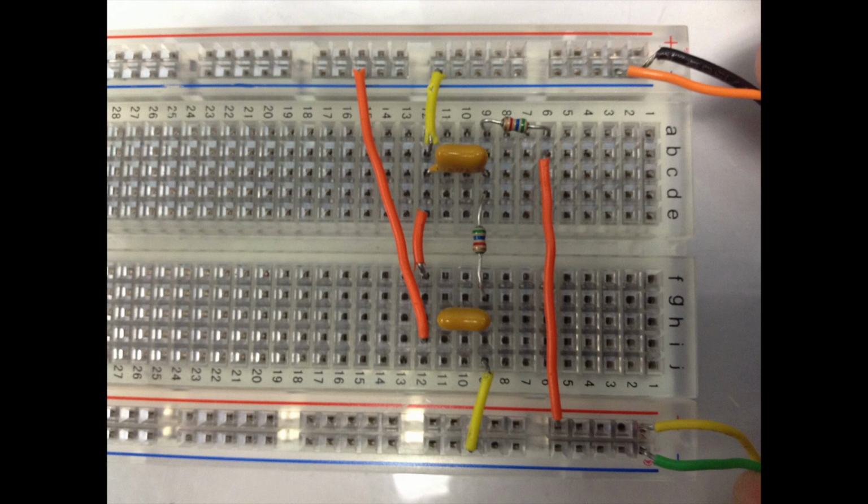This filter was built using a breadboard, and you can also use the recommended resistors and capacitors. However, in order to minimize noise, larger resistance and capacitance is recommended, which will increase the filtering and provide fewer ripples in the data. Using larger resistors and capacitors will cause the signal to lag in response time. The minimum resistance for R1 and R2 stated by the datasheet is 4.7 kiloohms. However, we chose resistors with 5.5 kiloohm resistance. 10 microfarad capacitors were used for C1 and C2.